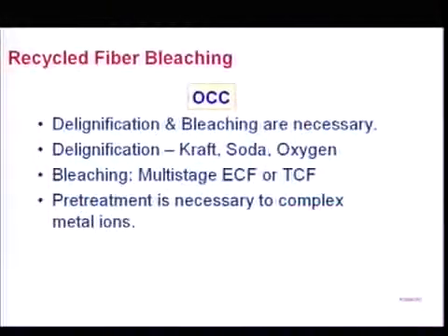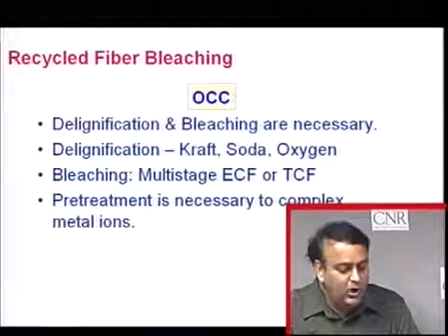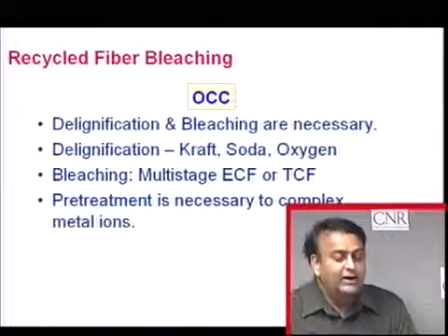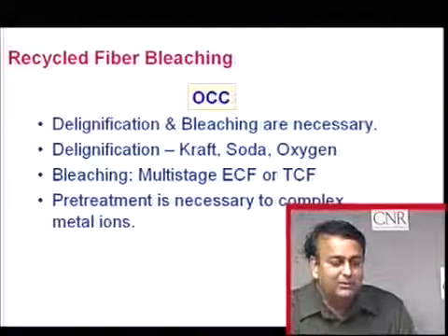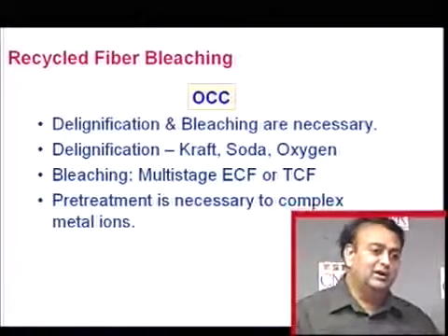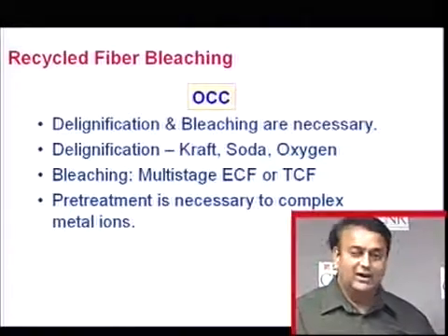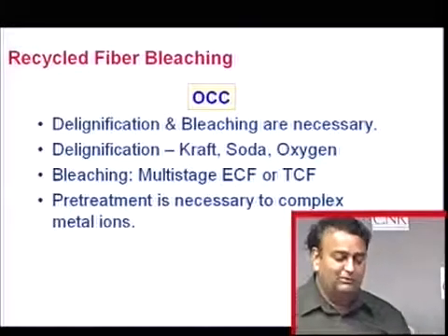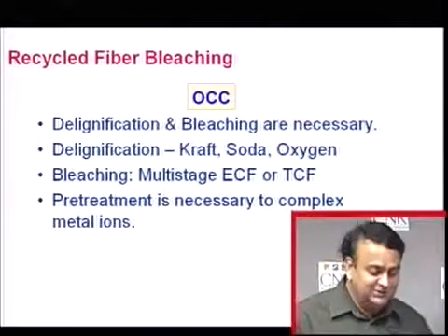OCC, old corrugated container. Now, let us take brown fiber. I want to make white fiber. I need a delignification process because I have lignin present in that. Unless I remove that lignin, I am not going to make it white. So, you can cook it by Kraft process, soda process, or oxygen, multiple stage oxygen delignification. I have seen up to 3 stages.